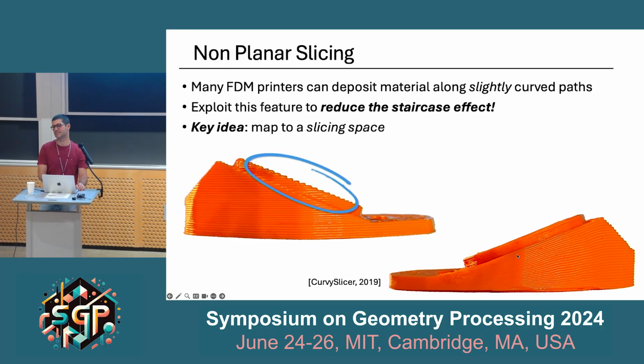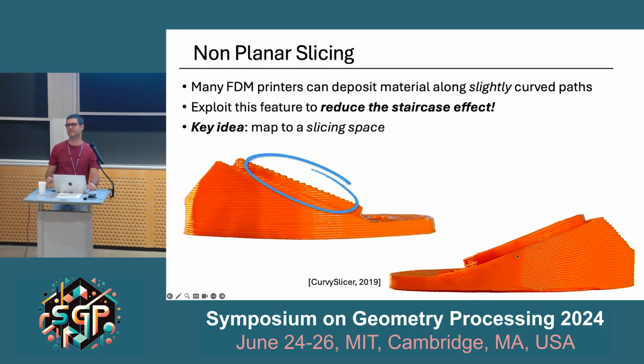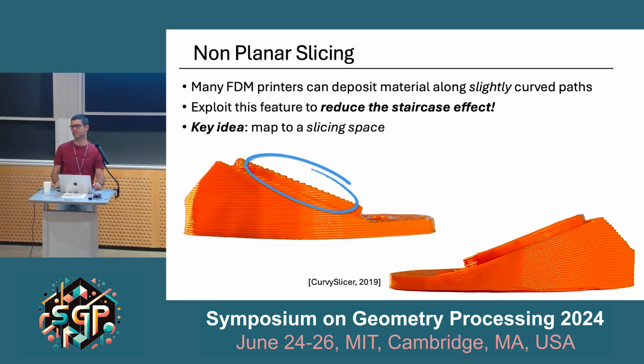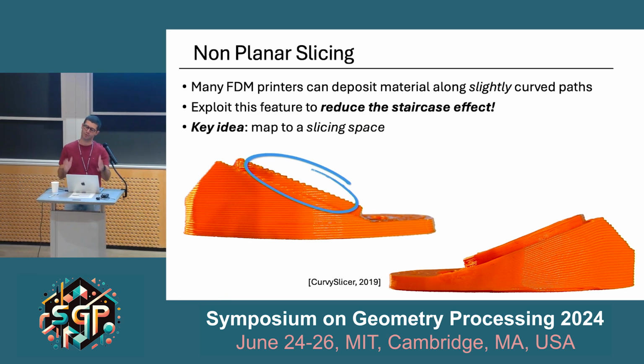So these are classical extruder filament printers, and they have some degree of freedom because on some of these printers, for example, you can tilt the plane, you can play with some parameters, so they will give you some flexibility. With stereolithography, you are more constrained because of the surface of the resin in the tank. Even if you tilt the tank, it doesn't really work.